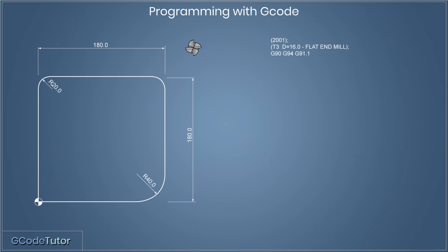So if we're at the start of a radius and the center of the radius is 10 millimeters to the right of the cutter, we would give it a value of I10. I, J and K are used to define the center points of radiuses, and they mean the same as X, Y and Z. So I is X, J is Y and K is Z. We'll talk more about that later in this lesson.